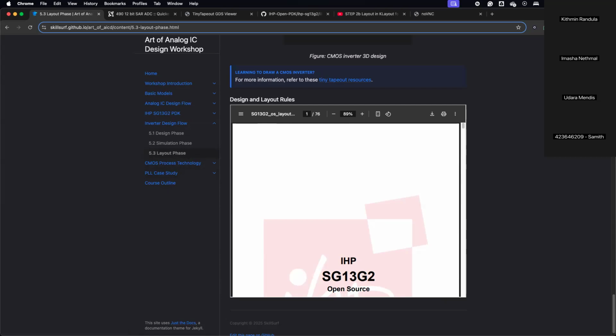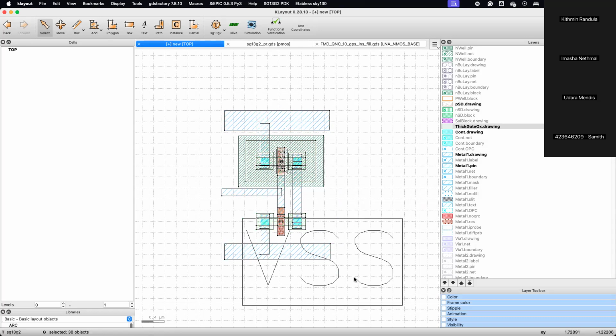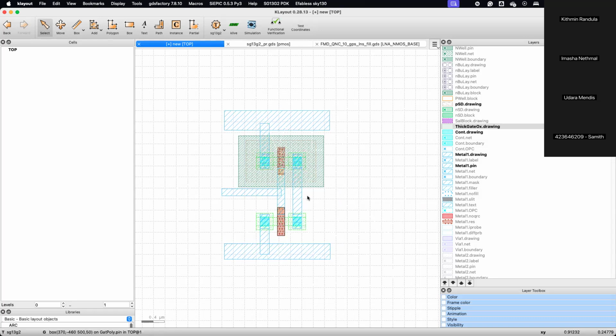Oh, there's a question. Sorry, I'll just answer this question quickly. Can you explain the Xschem drawing and the KLayout layering connection? Is anything like netlist import, or is it purely drawing the layout manually? Yeah, you're asking a good question. So how do I know I drew something correctly? I have my schematic, and from the schematic I visually understand, and I try to draw the same thing here.